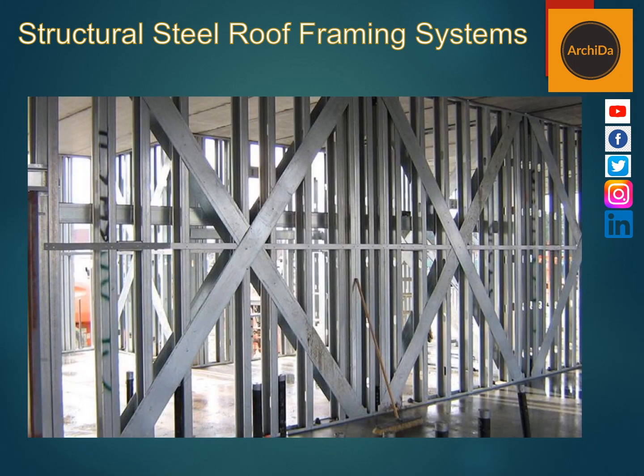Wall bearing framing is suitable for the construction of low-rise structures. This is because the size of the bearing wall must be increased significantly to withstand the considerable loads exerted in the case of multi-story buildings. This problem might be solved to a certain extent if reinforced concrete walls are applied.